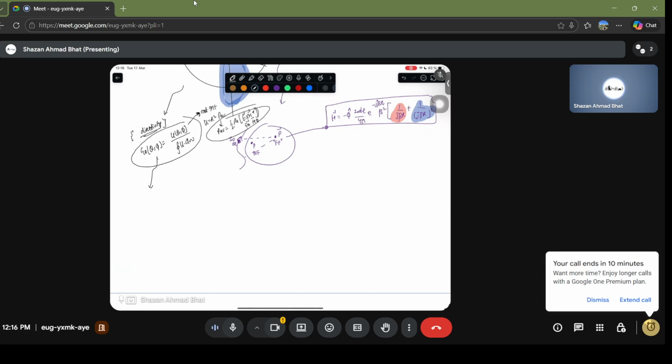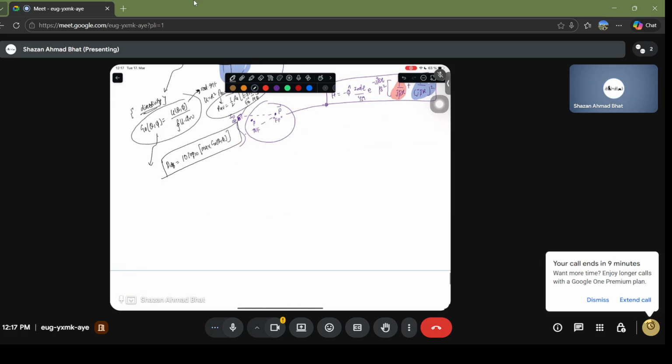And if you are given directivity, this is essentially not the directivity in decibels. You can find the directivity in decibels by taking the log of this quantity: 10 log to the base 10 of the maximum of G D theta comma phi. So this is exactly the directivity on the decibel scale. Okay.